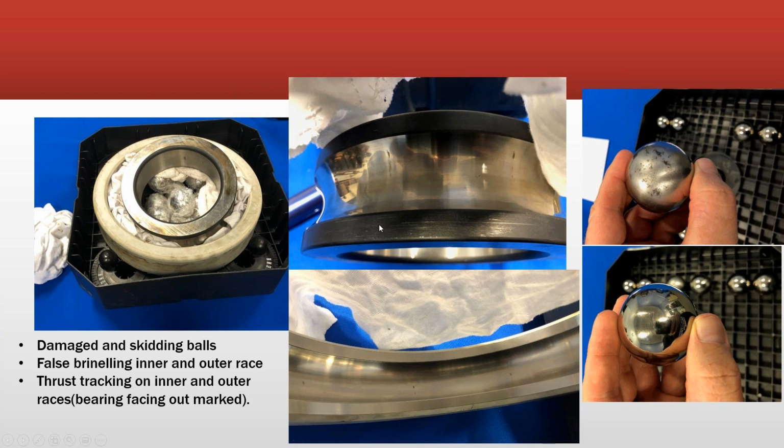In any case, we were seeing false brinelling on the inner and outer race, basically. These don't look like much in the pictures, but they're pretty rough by hand. So those were actually visible with vibration as well. One of the balls was skidding, so it was already starting to flake, and this is what they should look like here. Some of these were getting caught in the cage. I don't have the cage, or did not have the cage, to look at that as well. So those are the signatures we saw. We had two like this, the rest were okay. And these are pretty sizable.